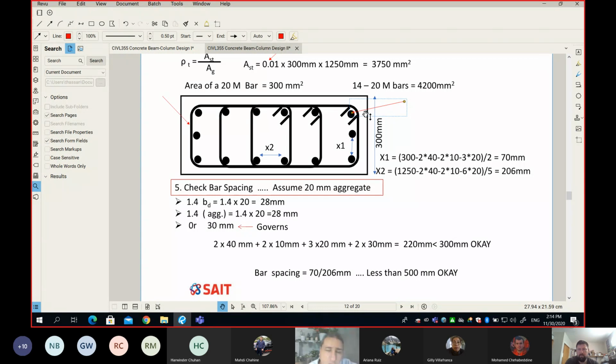This bar is always confined and restrained by the core, by the tie, because it doesn't go in the X or in the Y. Look at the shape of the tie, it cannot go anywhere. It cannot go to the outside. I'm going to point out, this guy is wanting to go outside this way. It cannot, because of this exterior tie.